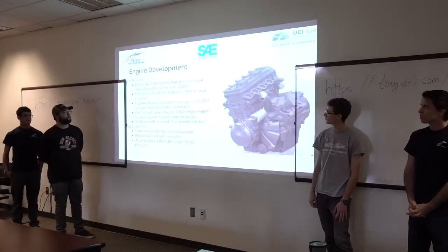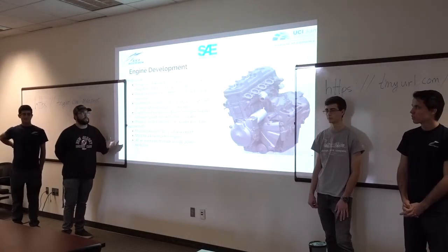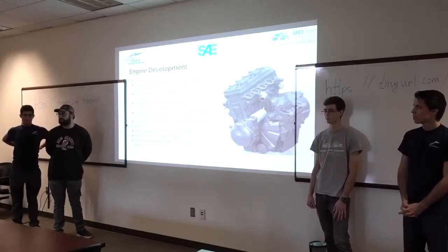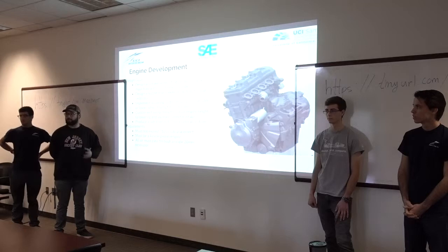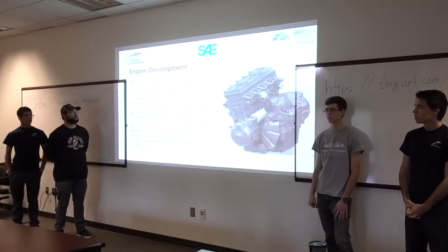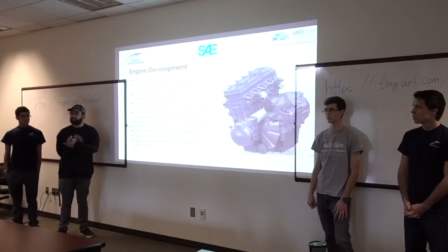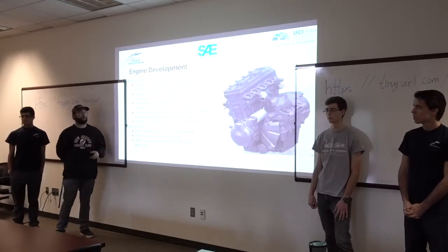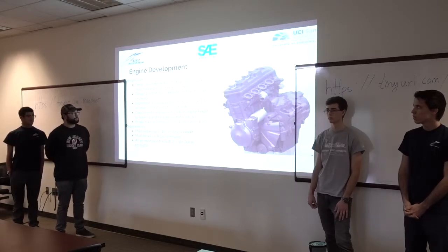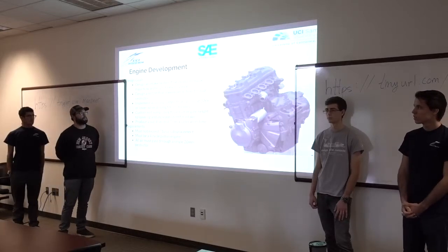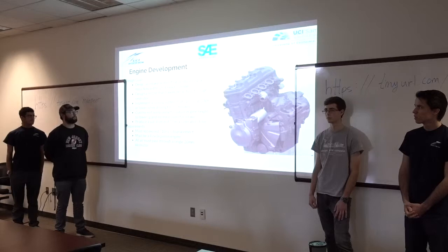For engine development, we plan to design an intake system that would flow within 2% to each cylinder. If you're not flowing within 2%, or really the max is 5%, you'll produce less power from one cylinder to the next and create an oscillating power into your crank, which reduces overall power in general. Design a nozzle that maximizes airflow into the restrictor.